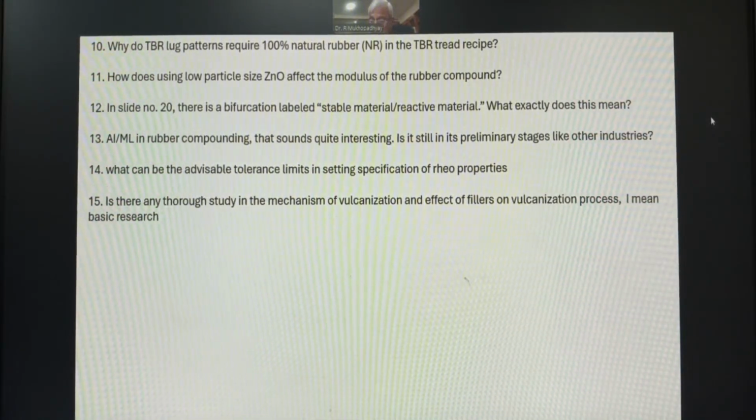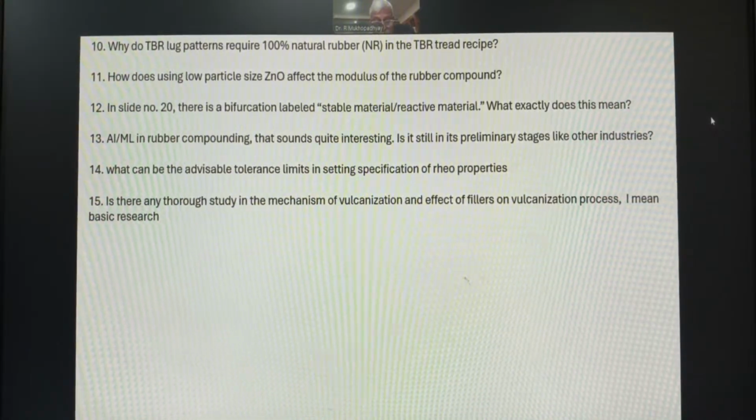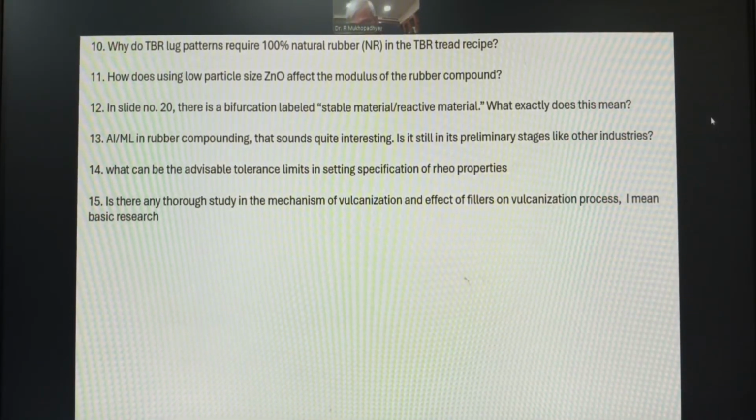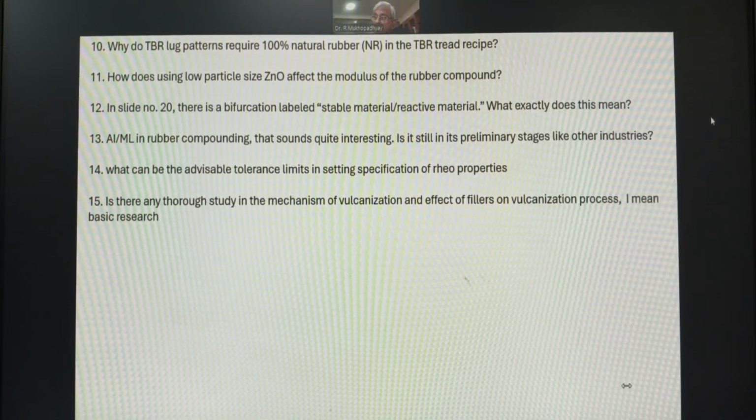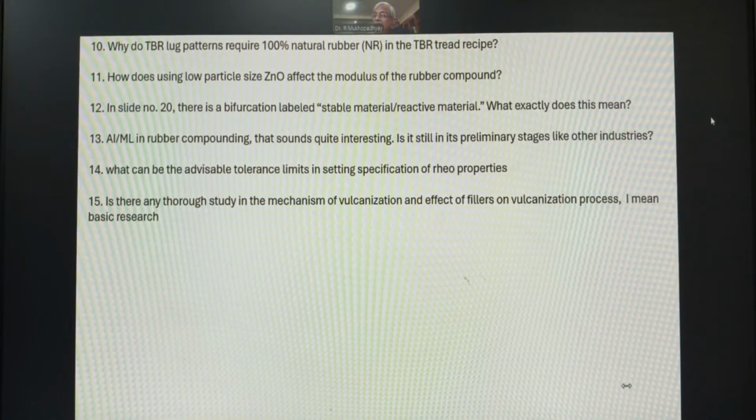whether it's a tire compound or a non-tire compound, normally you have to control the frictional heat generation, which is how the heat will be taken out. You have to consider the flow rate of the water, and also what the heat generation is, the amount of heat you want to take out. It is mass times specific heat times delta T. So the volumetric flow rate of water is important, quality of water is important, and scaling has to be cleaned at a certain frequency for the cooling system to be effective for any rubber equipment, whether it's an extruder, a calender, a mixer or a mill.